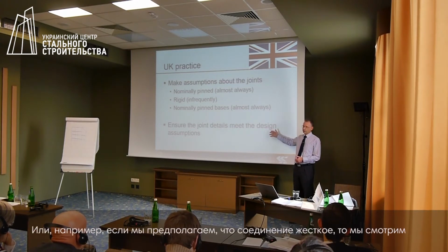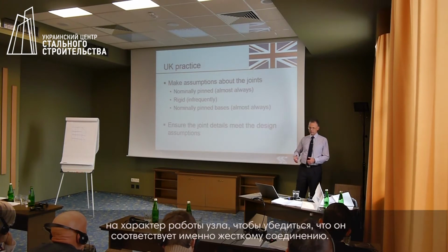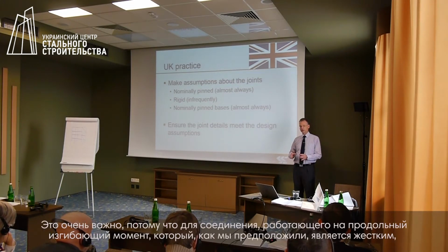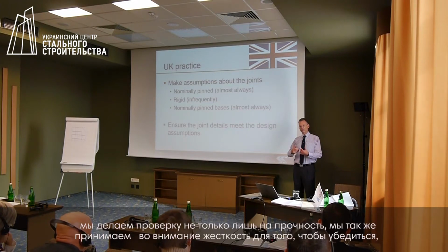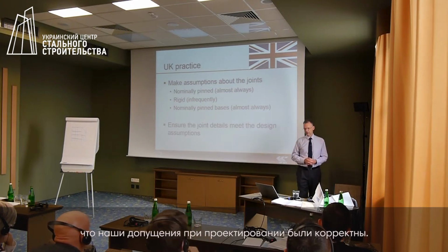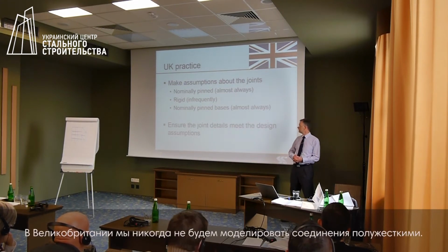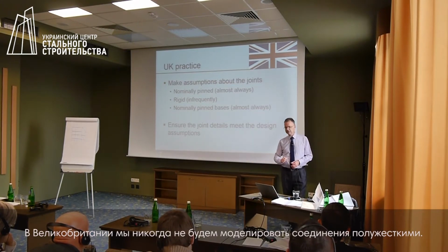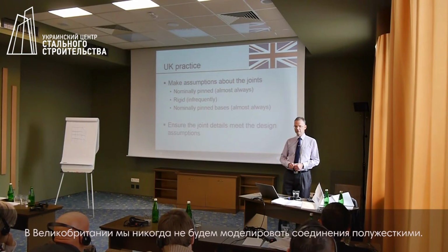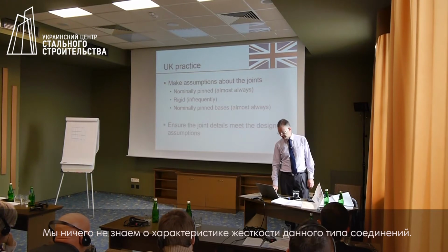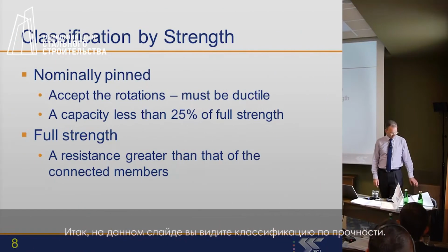Now, that may be important because for a moment-resisting connection that we have assumed is rigid, perhaps we do not design just for strength, but we also consider stiffness to make sure that the assumptions made in our design were correct. In the UK, we would never be modelling semi-rigid or semi-continuous connections. We don't know anything about the stiffness of our connections. So here are the classifications.